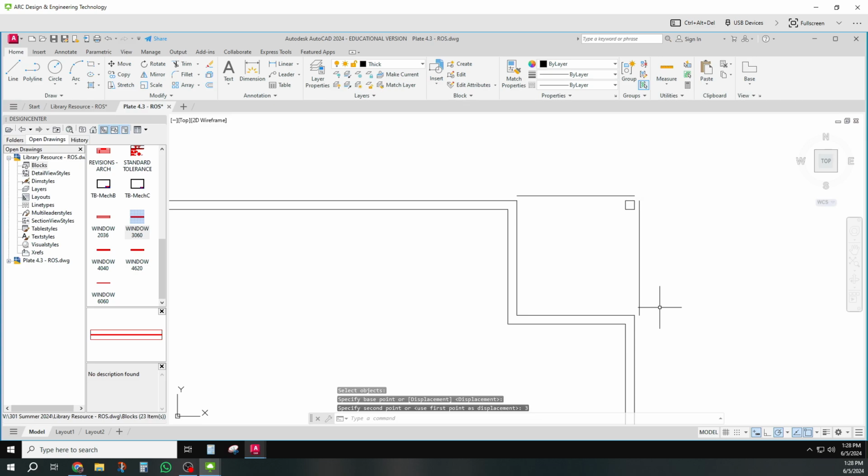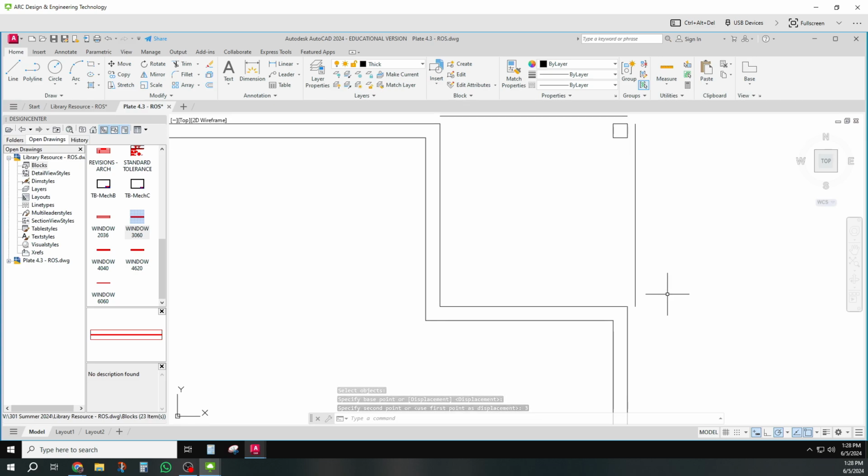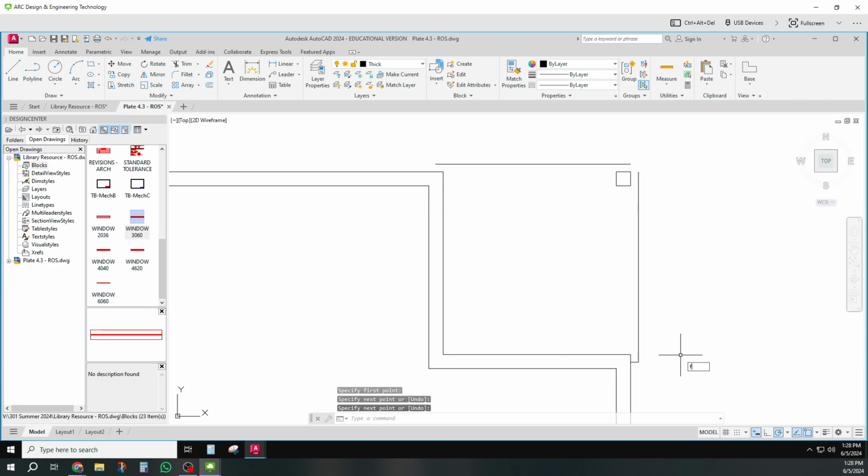And I'm going to do another new command. It's called lengthen. Lengthen DE delta 3 inches. And then I can lengthen that 3 inches and lengthen that 3 inches. And now I can finish that little part of the drawing up. Isn't that a cool little command? Lengthen. And up here, I think I'll just use the fillet command.